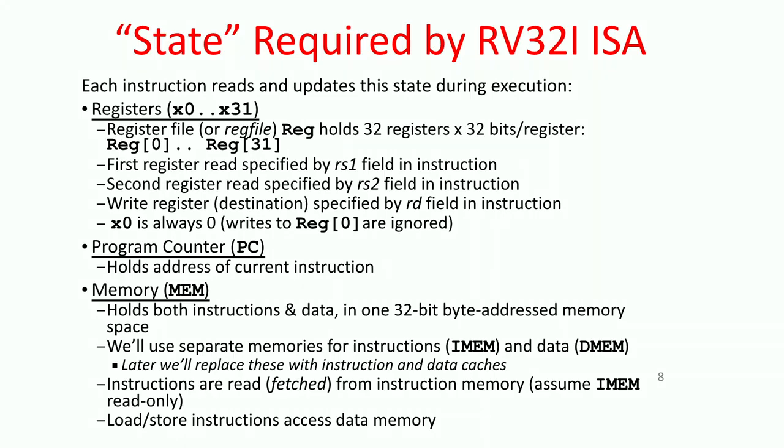Whereas if we had to move operands from memory into the data path of the processor all the time, the whole machine would run slow because there's a long delay to get to the memory, partly because there's a lot of capacitance on the long wires getting to the memory, and the memory itself is very large and very slow. So modern day processors use register files, and most of the operands for most of the instructions come from the register file with the result going back into the register file.